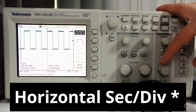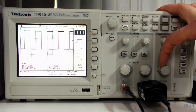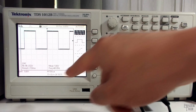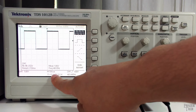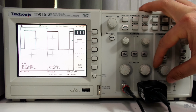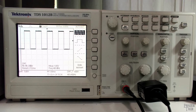Now let's talk about horizontal position. So this basically works the same way. It adjusts the scale, but this time it's on the x-axis. So if I were to move it clockwise 1 notch, we can see the signal is stretched out and is bigger. And we will also see this M is now reading 500 microseconds. So now each square represents 500 microseconds, as opposed to before where each one represents 1 millisecond. It's just adjusting the scale.